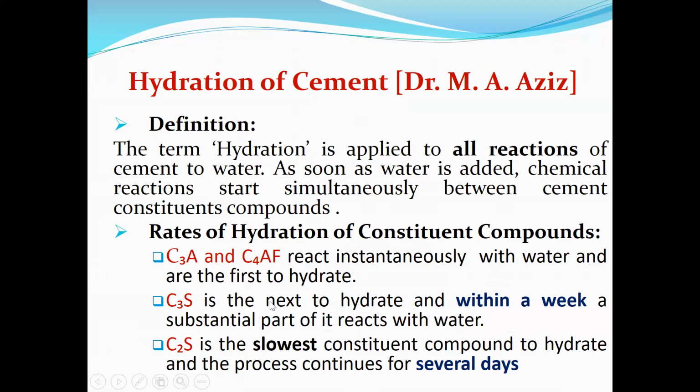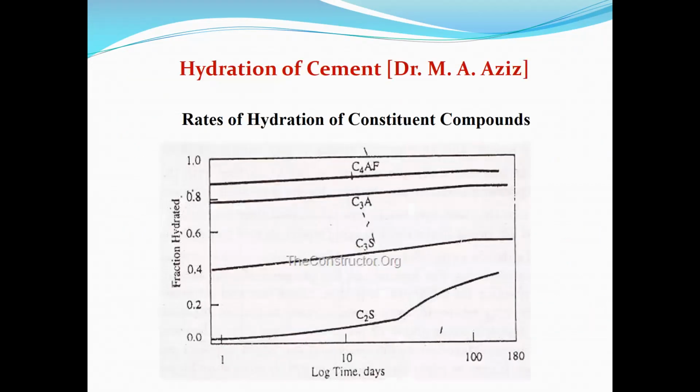Out of these four compounds, C3A and C4AF, they react instantaneously with water, and they're the first to hydrate. Then C3S is the next to hydrate, and within a week, a substantial part of it reacts with the water. And then C2S is the slowest constituent compound to hydrate, and the process continues for several days.